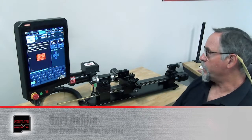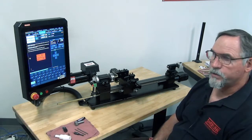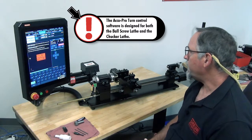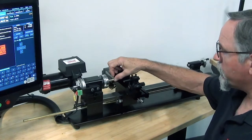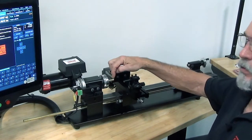We're going to go over some things to consider when you're programming as far as your tooling and the way it moves, and also park position. Okay, so right now what I've done is I moved my cutoff tool past the center line in X, and it's about 50 thousandths away from the front of the tool.